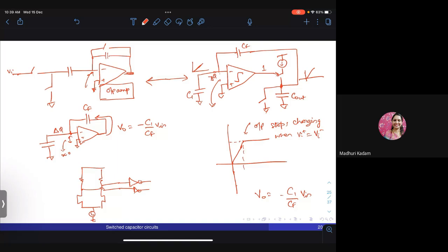The same techniques which are used to compensate for offset of op amp can be used to compensate offset of comparator also. Okay. And as I said earlier also, offset errors are generally not very troublesome. They are easy to correct for, because it's just a fixed value, fixed DC shift, unlike non-linearity, which is very difficult to compensate for once it comes into the system.